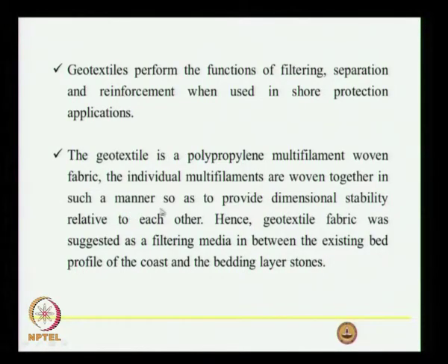This is a polypropylene multi-filament woven fabric. The individual multi-filaments are woven together so that it provides dimensional stability relative to each other, and that is why we suggested this as a filtering media. In earlier days they used sand itself as a filter media where we have a clay bed, but this is a better material. The cost is not very high, maybe around 100 rupees per square meter now.